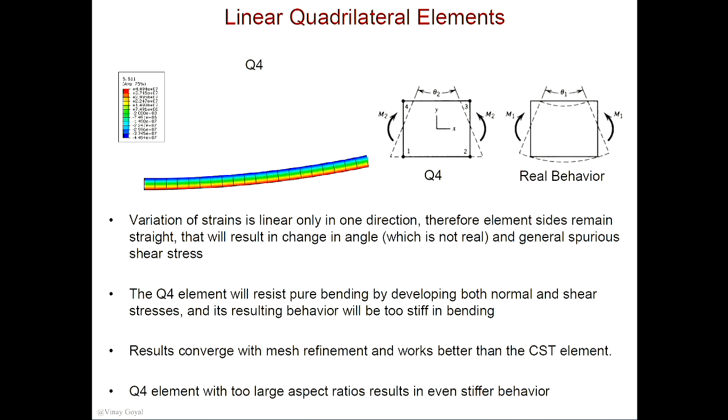The linear quadrilateral element, a single Q4 element across, will also behave a little bit stiff. The reason is that the bilinear displacement field we have chosen does not allow you to represent curvature very well. It only allows you to model this kind of situation, and does not allow you to model this situation. So for that reason, you're also going to have an overly stiff behavior, and some amount of shear locking in this type of element.